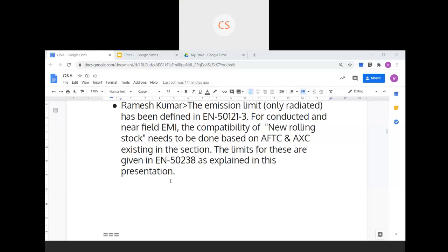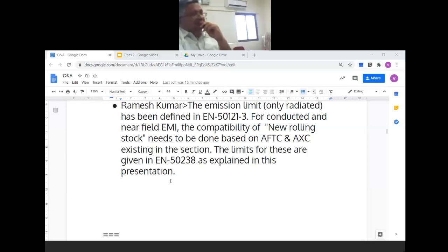Correct, sir. So APC, I don't think it is deployed anywhere on Indian Railways. I'm not sure, but this is an example I quoted for that question of panto lowering and going back in neutral sections. In that system, they install a magnet just before the neutral section and another one after it. That is picked up by the locomotive, and it switches off or disconnects the circuit for the OHE current. When it has gone beyond the neutral section, it again gets the signal from the magnet that you are now beyond the neutral section, and it connects to the OHE again. That's a very simple thing. It is independent of signaling and has nothing to do with signaling. There is a small receiver on the underframe of the locomotive, and there is a magnet on the track, and that's how the information is picked up.